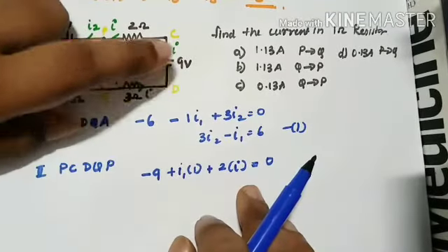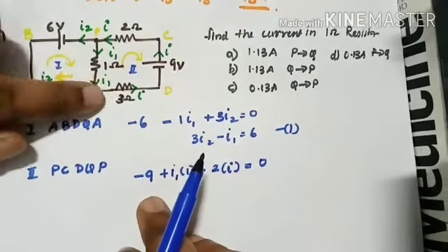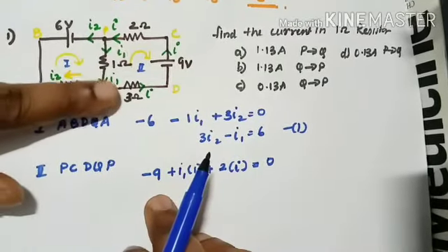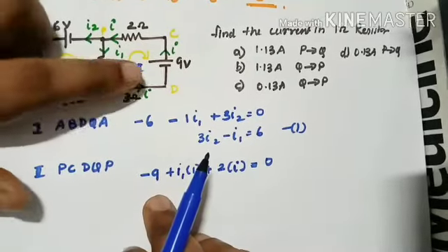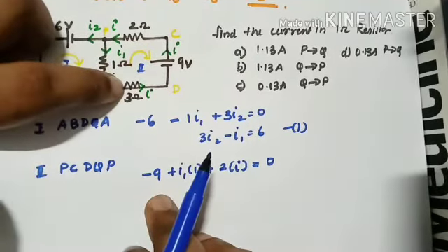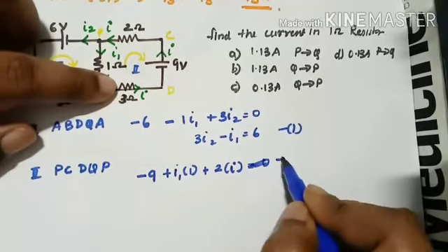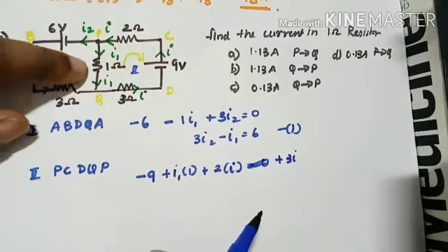The 9-volt battery, positive to negative, so minus 9 goes off, then reach 3 ohm resistance here. Right, I think I missed this 3 ohm earlier. In the picture, there is a 3 ohm resistor here. Now current is in this direction. I'm moving in the opposite direction, so it becomes what? Oh, I did it right now. So it will be plus 3i. Right. Then it moves off and then it reaches 1 ohm.